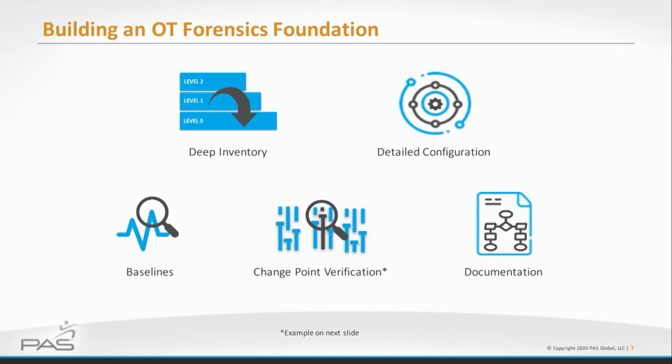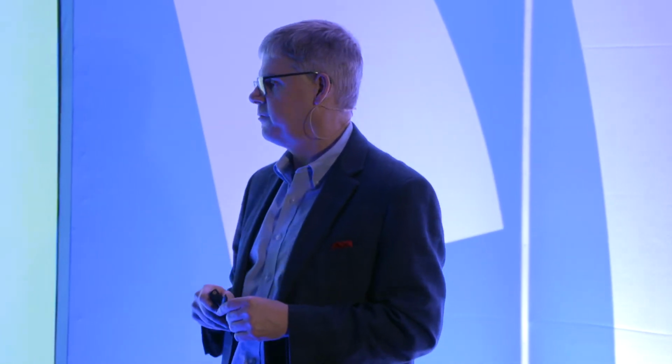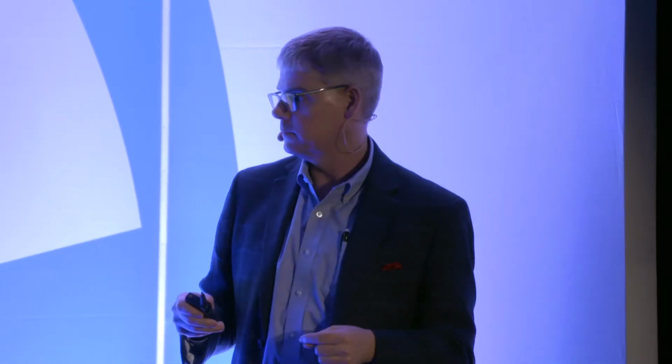I need all the information about all the controllers, the PLCs, which are basically special computers that run in that environment. What is their configuration, all the programming therein? That's what detailed configuration is. All of the information, and I mean extremely detailed. Here's all of my tags and the properties of those tags, and it's a flow controller with this gain setting that talks to this totalizer, whatever. You got to have all of that.